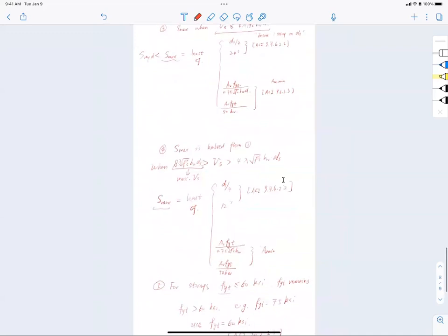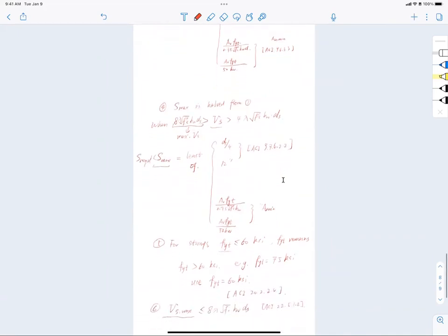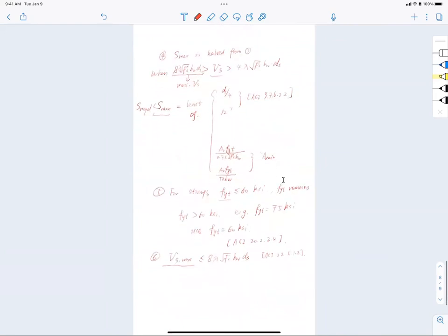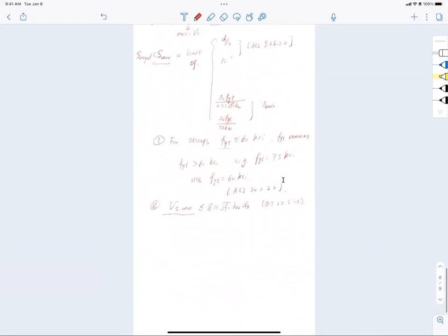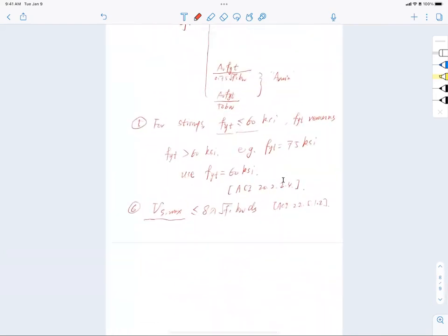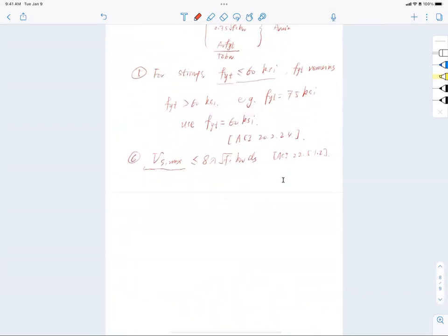Okay. And then if your shear resistance falls in the second category, you need to say that, look, this is falling in this category, so it has to be smaller than these sets of maximum spacing. And make sure your stirrups are within 60 ksi yield strength, and also make sure that your total shear resistance from the stirrups is bounded below 8 square root f'c bw d. Okay.